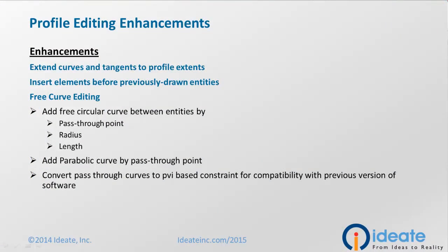Let's quickly review what we talked about. There are multiple additions to editing profiles in Civil 3D 2015. First, you can extend curves and tangents to the profile extents, which does not mean extending it to the horizontal alignment geometry. You can insert elements before previously drawn entities, and there are multiple free curve editing options.